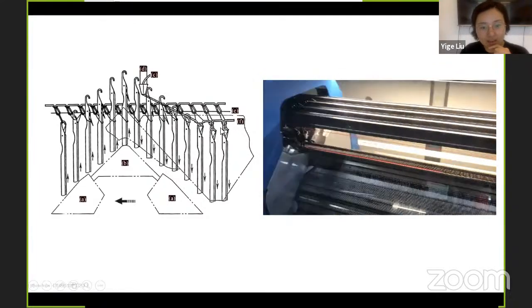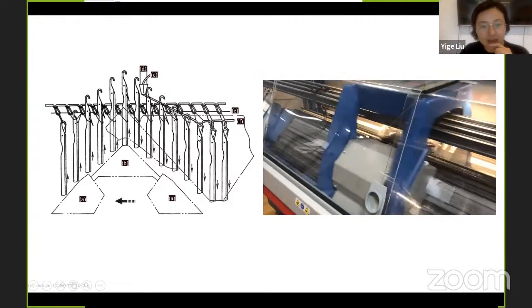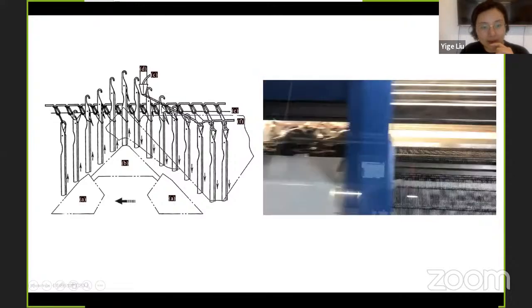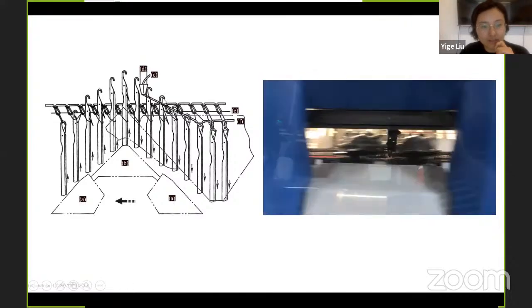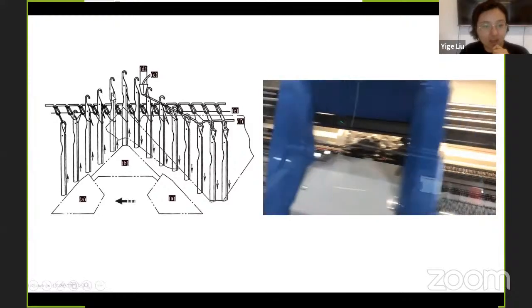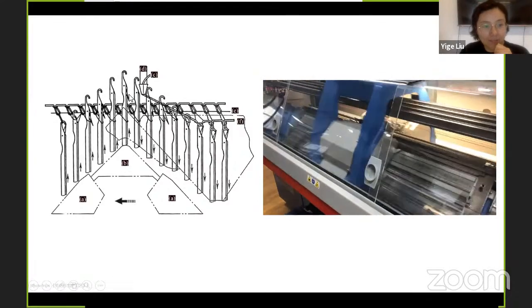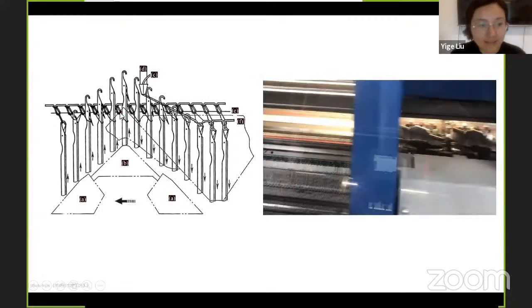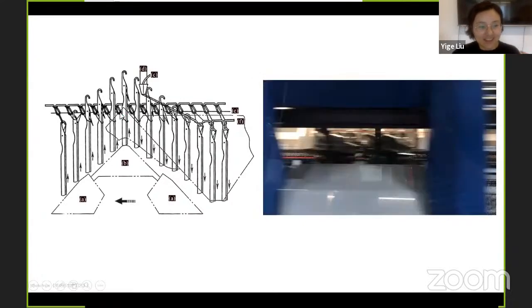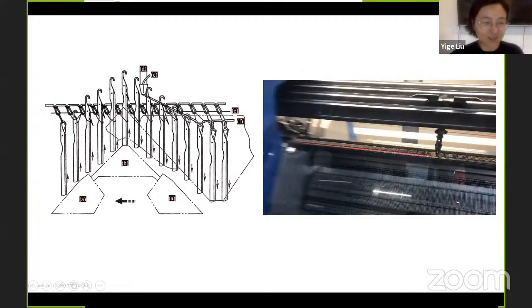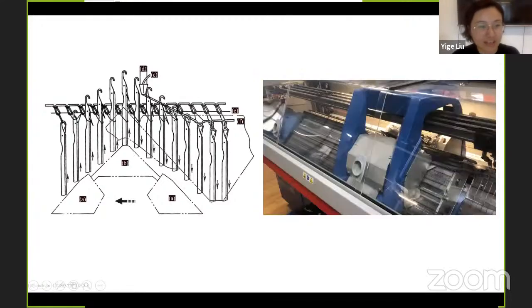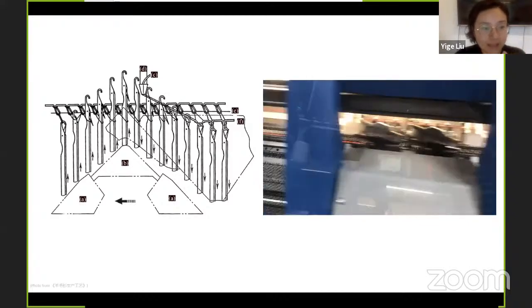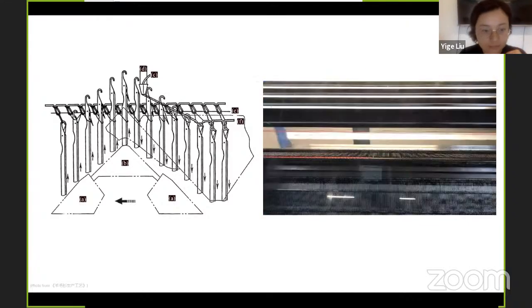Like this is a yarn that is newly fed. By moving the needles upward, it can open its mouth and the yarns are fed into the hook on the top, and then the needles will go downwards, and its top can close its hook, so the loops can be formed and interlocked with each other.